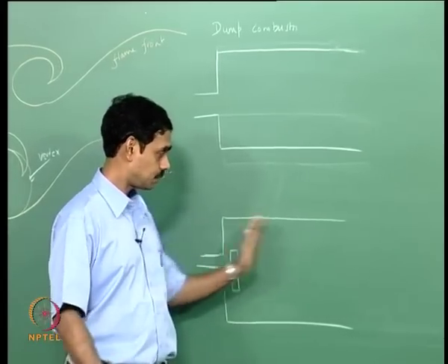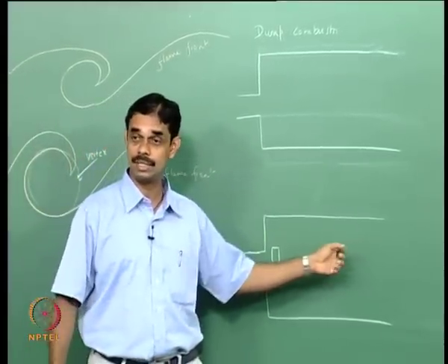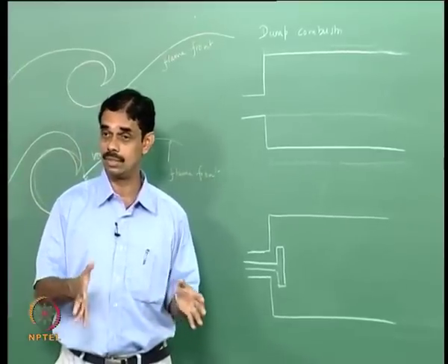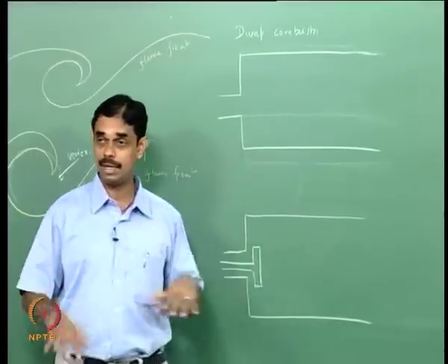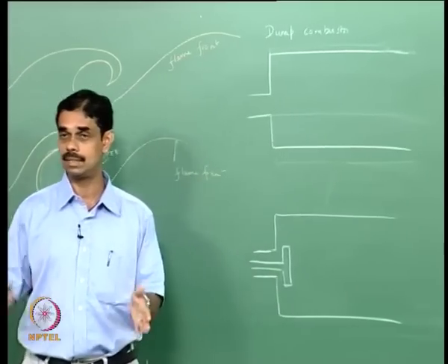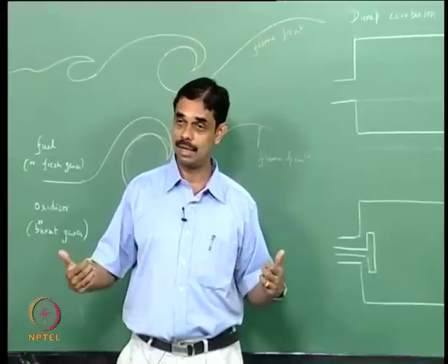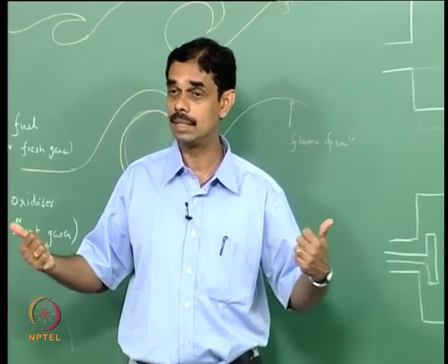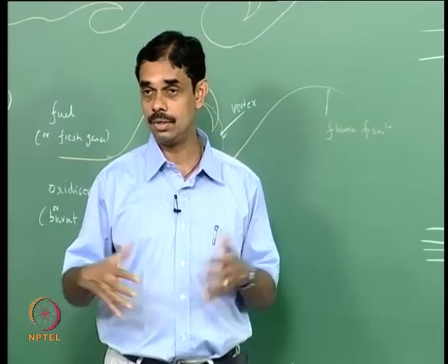So if your frequency is going up and coming towards the frequency of the acoustic oscillations in the duct, that is, if you have certain preferred duct frequencies, the natural modes, and you are coming towards that, then this vortex shedding will suddenly lock to the acoustic oscillations, and then this instability can happen. But if you are going away, then the chances of these coming closer are lower. It does not have to match exactly, these are nonlinear phenomena, so you just have to come close. If both frequencies are going away from each other, then you are actually detuning the system, and you will not have oscillations.